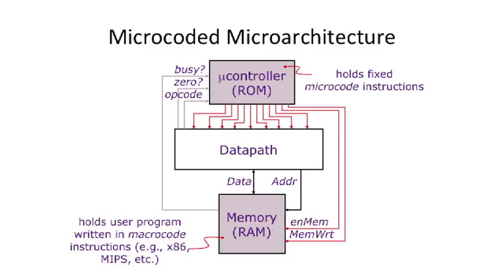Here is the micro-coded control unit, or the micro-control unit, hooked up to a micro-coded processor. So we have the data path sitting in the middle here, and we have a bunch of wires coming out of our control unit here, which assert different things on the data path. For instance, are you doing a subtract? Are you doing an add? And it's going to swing different multiplexers inside of this data path to select what operation is actually occurring.